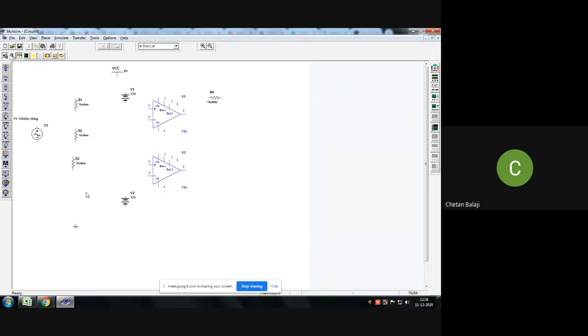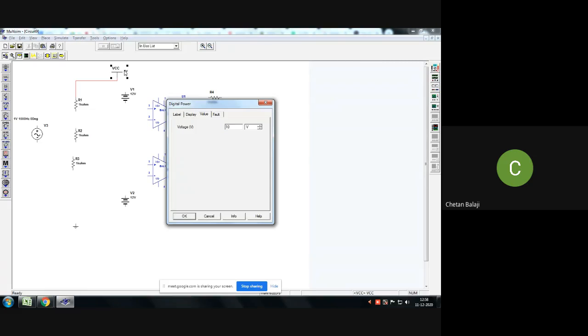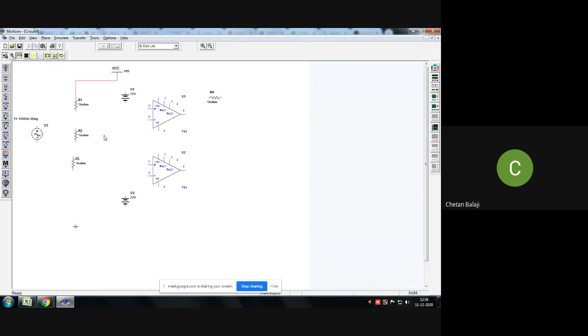Connect the top resistor to VCC. Double click on 5 and change it to 10. This is R2, just move it away. The default value of this is 1K. Let it be as such, because you can design for your own choice.